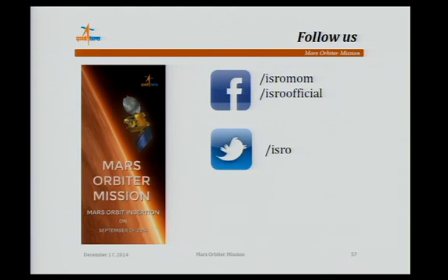Then auto tests like boundary checks, that type of normal tests, we carry out as such. Here, scenarios have been specially given for each functionality, each phase of the mission, and what things take place. For example, sequencers, where complicated timing and different options are involved. Each and every scenario, like when a fault condition occurs, what happens, then FDIRs, recovery sequencers, and operational sequencers, all those scenarios have been put and checked. Approximately around 10,000 test cases.